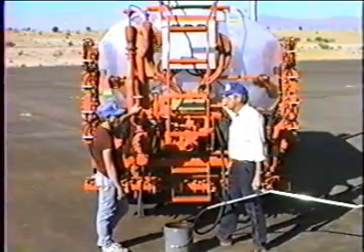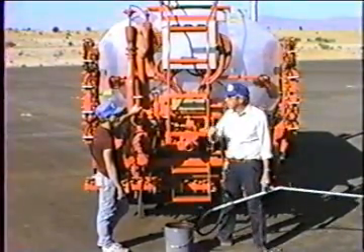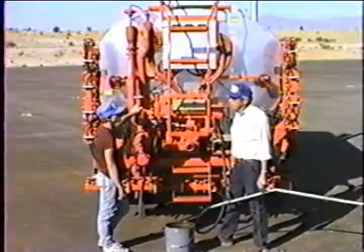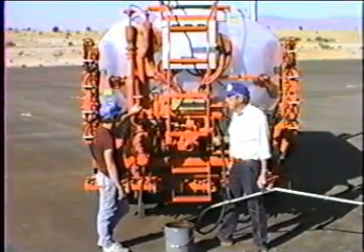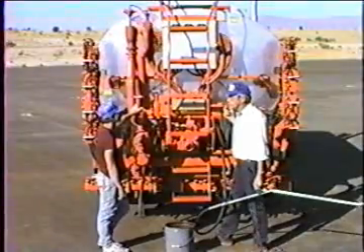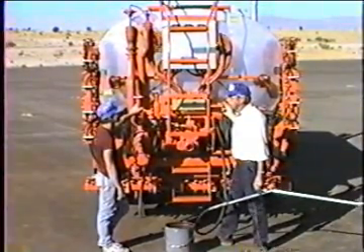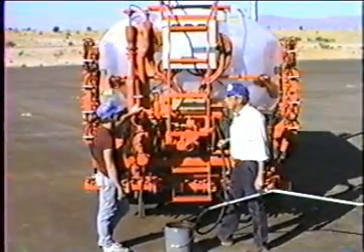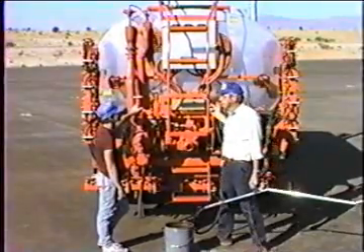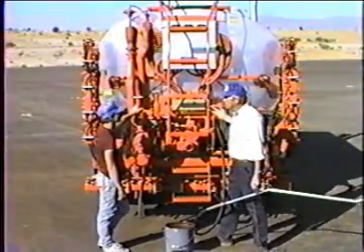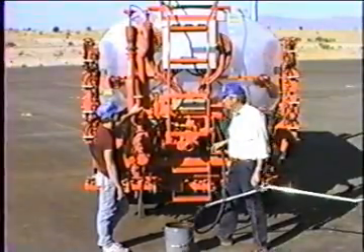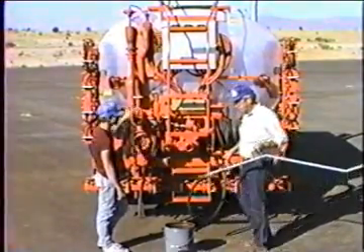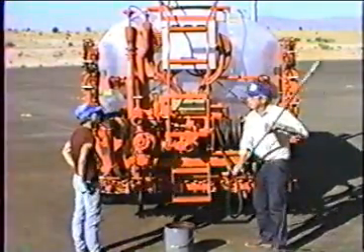So I won't give you a sample out of the truck, you've got to take your sample out of the trailer. And if he's a reasonable, intelligent fella, he'll do just that and everybody's happy. If he's not reasonable and intelligent and insists on getting out of the truck, your best thing is just to go on home, because he won't pay you for the asphalt anyway. Once he takes a sample out of an asphalt distributor, it's going to have some diesel in it. And if it doesn't pass the test, they won't pay you for it, so there's no use putting it on the ground if they're not going to pay you for it anyway.